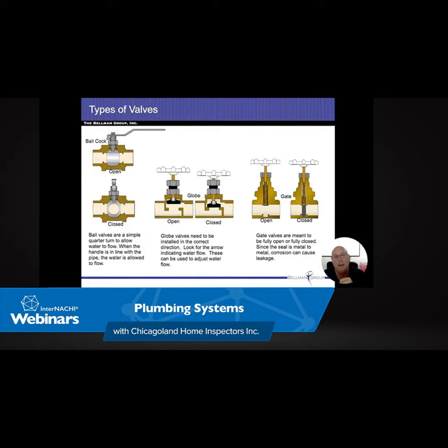Thanks, Mark. One of the things to put on that note too, and something that gives you that clue that that's happening, we call those gurglers. When the water heater is heating up the water and the flame is going, and you start hearing this gurgling sound coming out of the water heater, that's water underneath the debris, and it's turning to steam, basically. It's boiling, and that's lifting that debris up and dropping it back down again. That creates that noise. So you've got a lot of debris in there at that point, and it's either time to flush it or you're going to be looking to replace it.